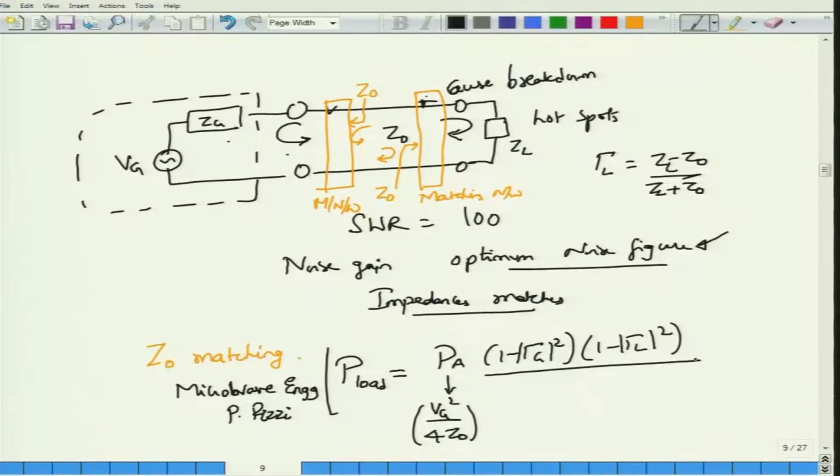And in addition to these two, because of this multiple reflection and propagation back and forth, there will be an additional factor of 1 minus magnitude of gamma G times gamma L e to the power minus j2 beta L, with a minus sign simply because I have taken Z equal to 0 here, and therefore the source will be at Z equal to minus L.